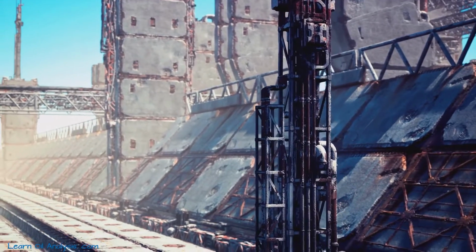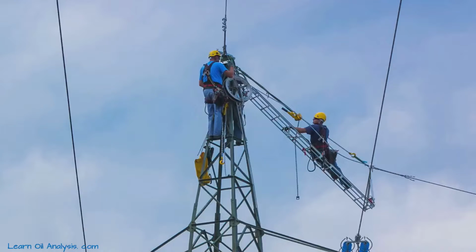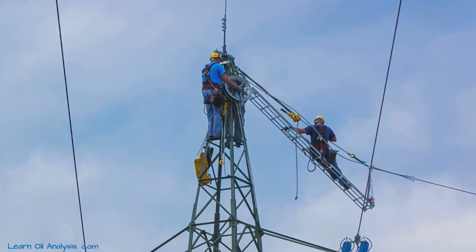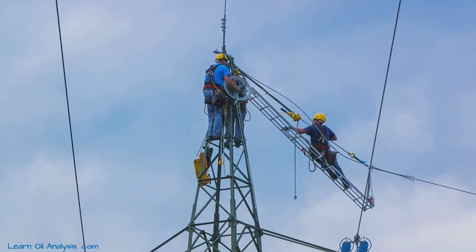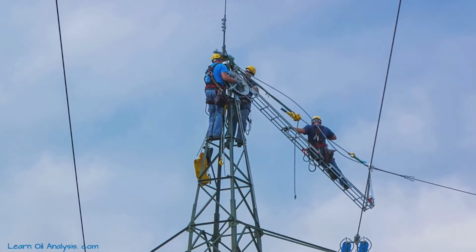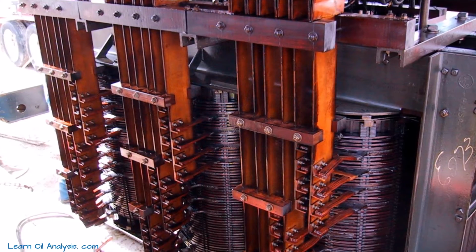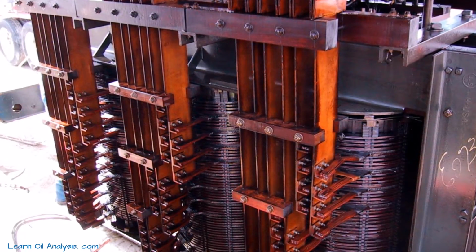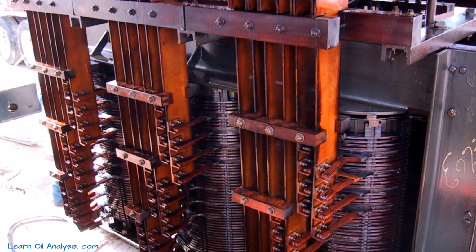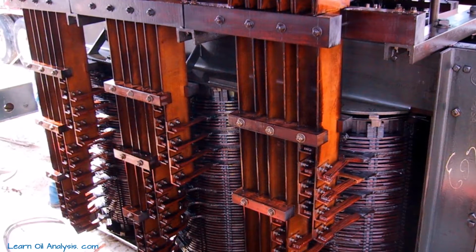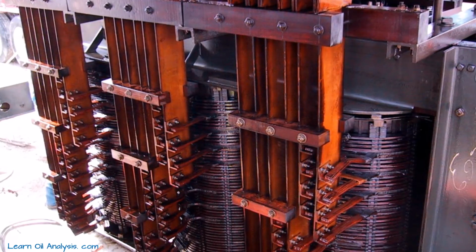So high temperature faults produce ethylene, whilst low and medium temperature faults, on the other hand, produce methane and ethane. These gases form due to the slow decomposition of oil at lower temperatures. Thermal faults can also be classified by temperature ranges, with varying levels of carbonization. The type and amount of gas produced are indicative of the severity and nature of the fault.